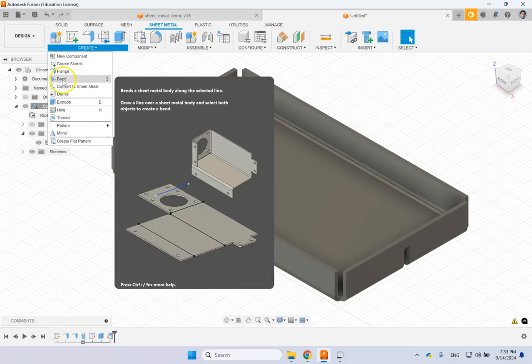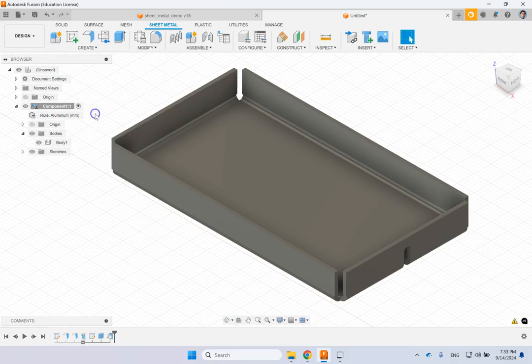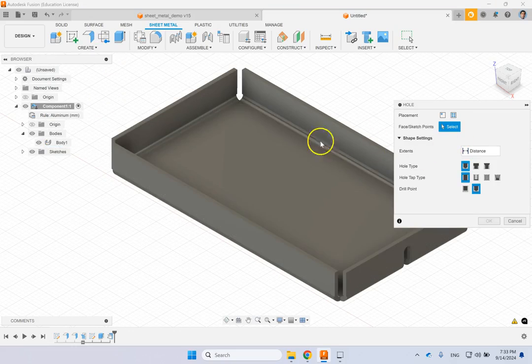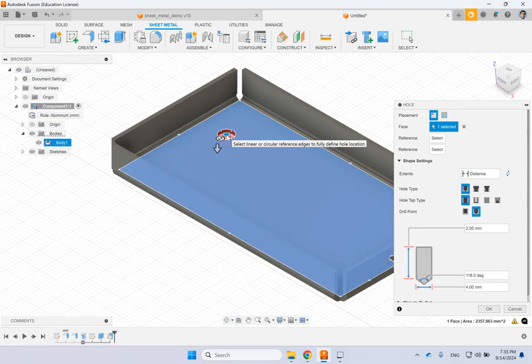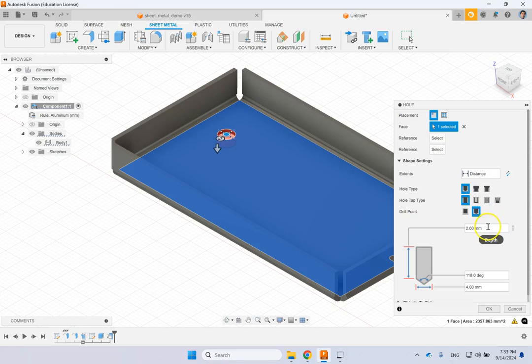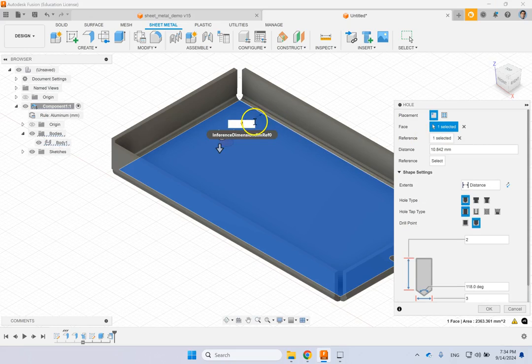And of course, you can create a hole on the object and you can pattern it too. So let's say if, for instance, you want to create a hole here, you can do that, right? Let's say the hole is just, and I make it 5 so it goes through, although 2 should be more than enough in this case. And the diameter of it is like 3 mils. And to place it exactly, I click on the references and provide the distances here, right?